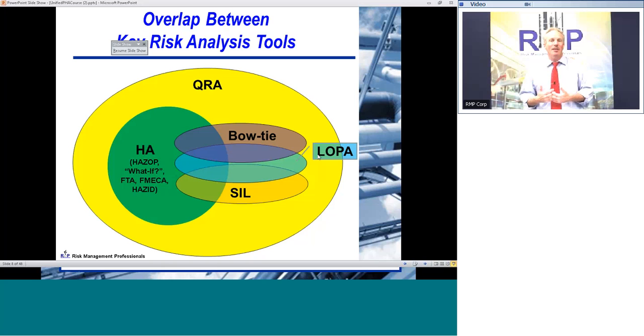Does that mean you do one or the other? What we typically find works most effective is doing the HAZOP study, and for specific scenarios where it's of interest, doing a LOPA right on the spot. As the team is understanding the situation and the scenario, go ahead and use that to glean additional information and provide probabilistic information that might be useful to the designer, or might be useful for identifying if you've acceptably met your risk criteria for the project.